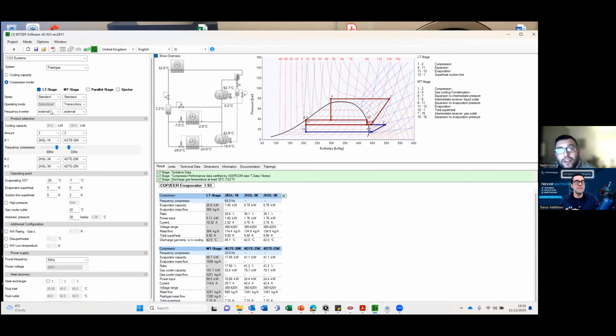Makes a big difference. It definitely makes a big difference. And then it keeps that suction nice and constant, keeps your whole system running a lot better than that one compressor turning on, drops all the way down to 66, and then the other one bangs back on. And I've seen that many times in HFC systems, but I think it's almost a norm now to put some sort of capacity control on a rack. Absolutely. It should be standard if it's not.